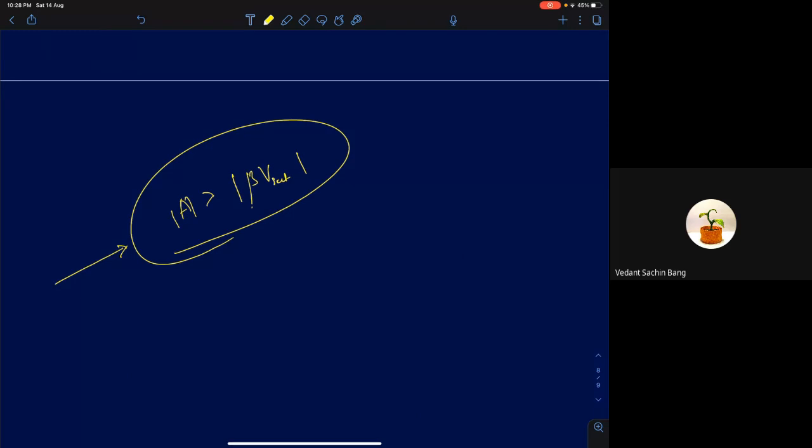Okay. So that's it. Very briefly, we discussed what a Schmitt trigger is. And we also spoke about sine wave to square wave converters. Probably at this point you don't have an understanding of noise, but still we tried to understand how we can have false triggering, how an op amp used as a direct comparator can end up giving unwanted rising edges, and how that problem is resolved when we go to a Schmitt trigger.